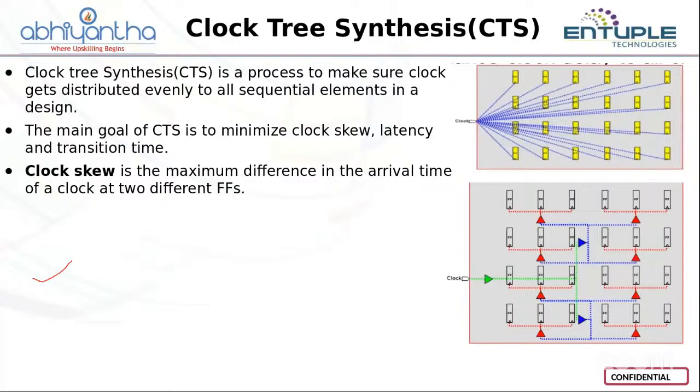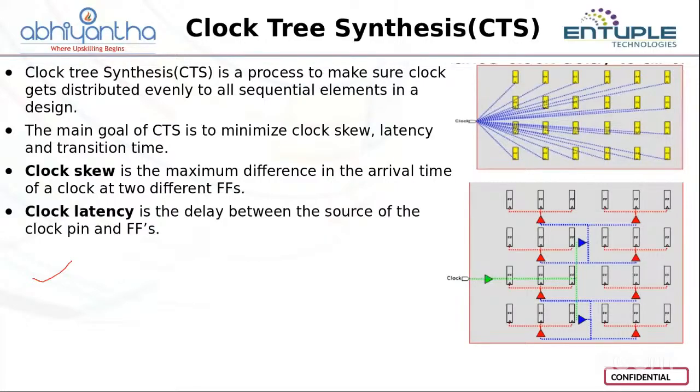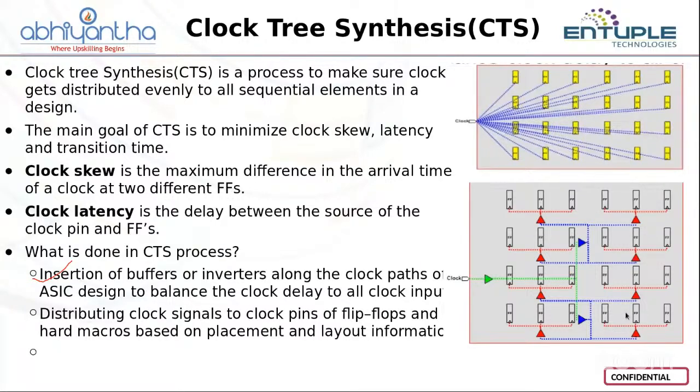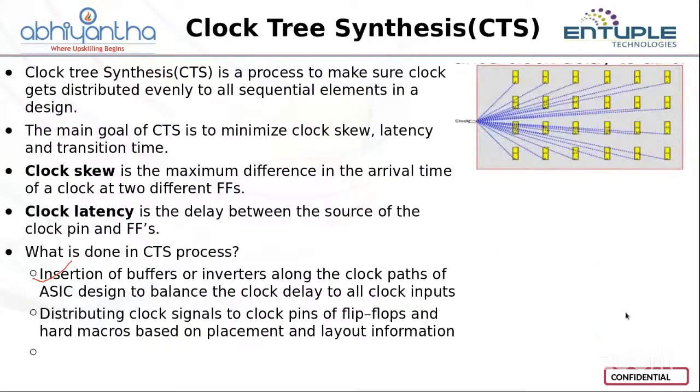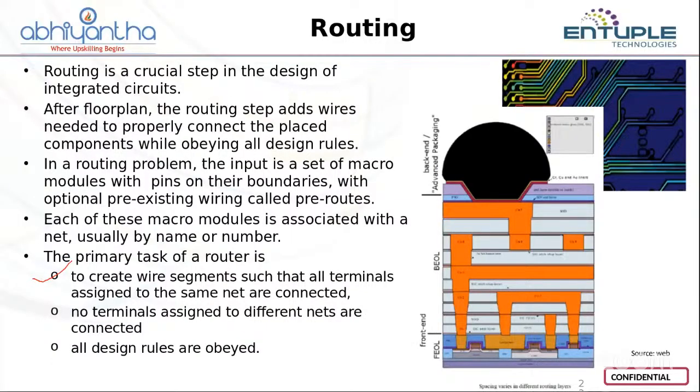As we mentioned, this should be optimized by inserting various buffers in between the logic. So you need to add it. Once this is done, your buffers will be added. After adding the buffers, you will get a uniform distribution of your clock.